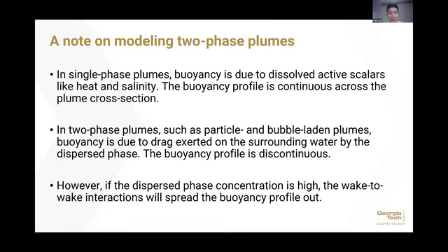But if the dispersed phase concentration, or the volume fraction, is high, the individual wakes behind the particles will interact, and that spreads out the buoyancy profile and makes it approximately continuous.